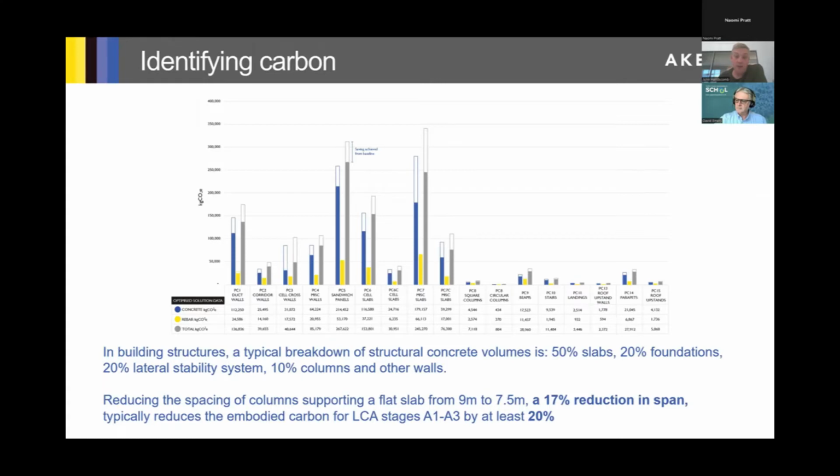Equally, a common grid, so a regular grid, taking loads down straight paths, delivers significant carbon savings. Structures that are offset, transfer slabs, cantilever structures, the carbon content to do those things increases rapidly because of the amount of structural elements that you need to support the building.